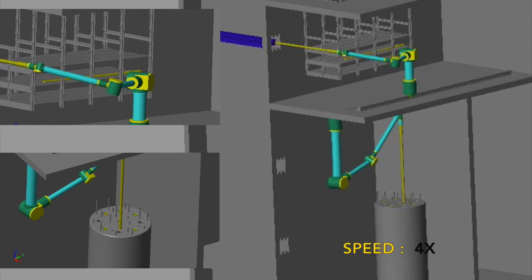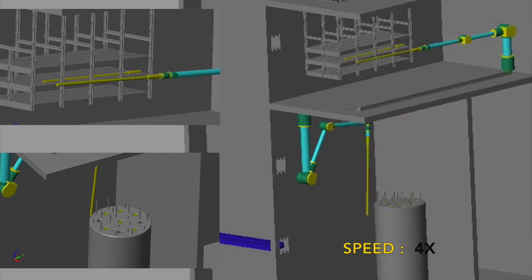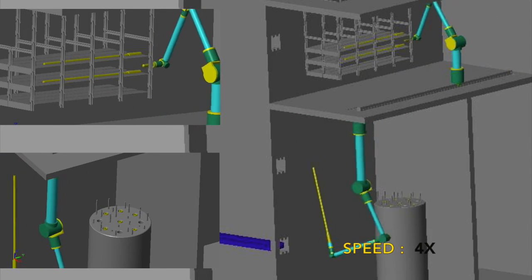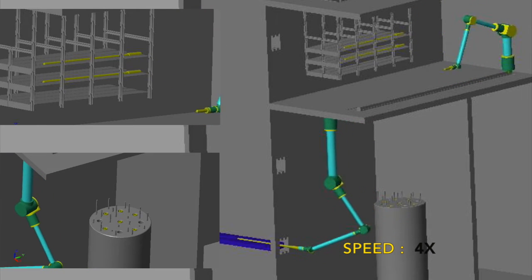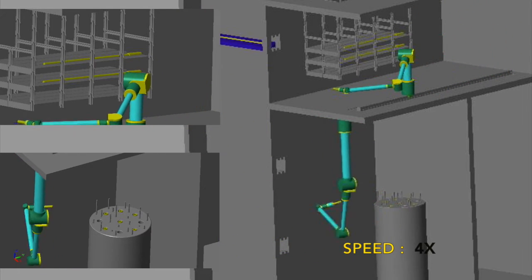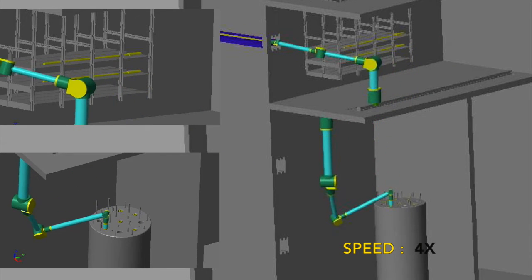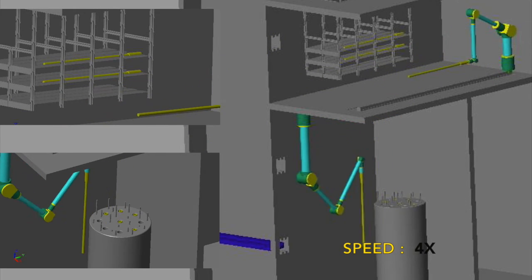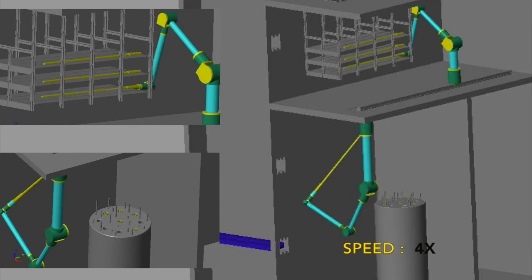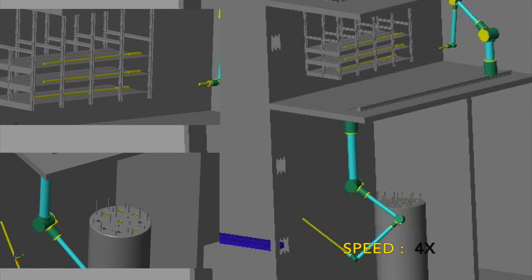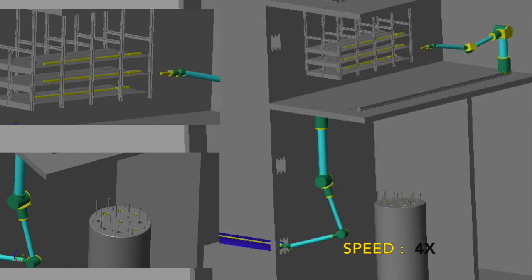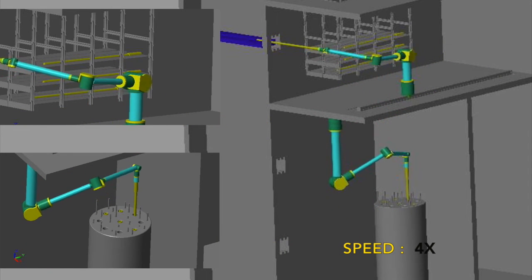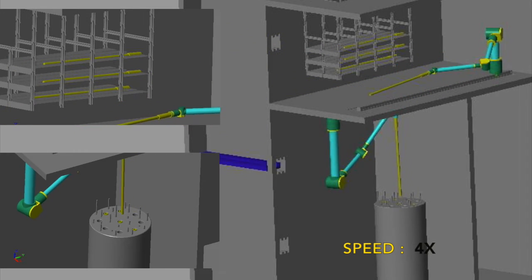The robot plant is difficult to control because it is highly nonlinear. As the robot moves from configuration to configuration, the dynamics change. This can cause instabilities in a standard PID controller unless different gains are calculated for every possible configuration. Due to these difficulties, our team decided to use a model-based controller where the torques for motion are calculated offline and then fed forward to the controller.